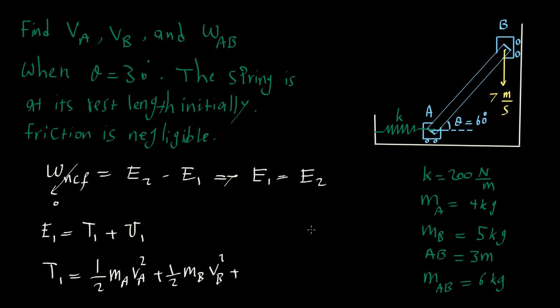And here is an example that we should be very, very careful about the point that we use as a reference, because there is no stationary point on this link. All the points on this link are moving. If we use the formulation for kinetic energy about point A or B, we have to be aware of the extra terms on top of 1/2 mv squared and 1/2 I omega squared. So here I would just go with the safest option, which is using the center of mass for this link as a reference point for calculating the kinetic energy.